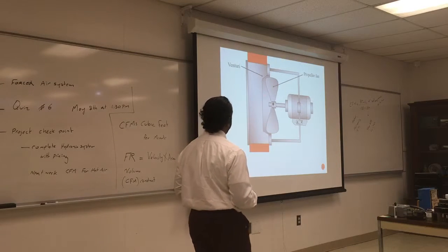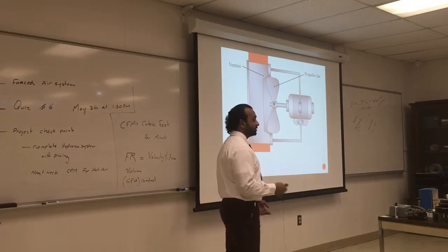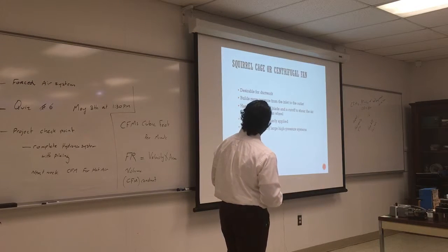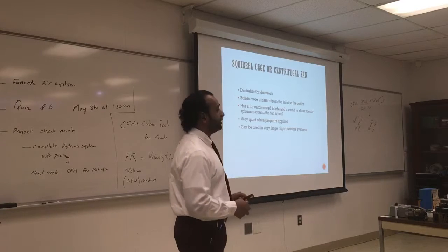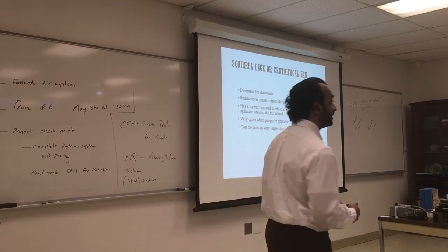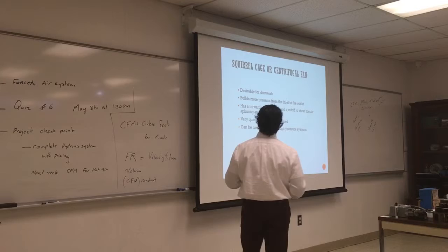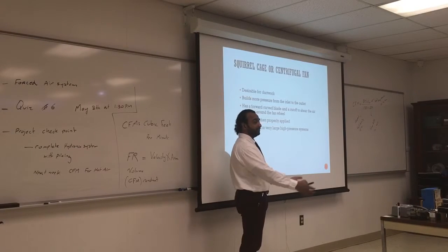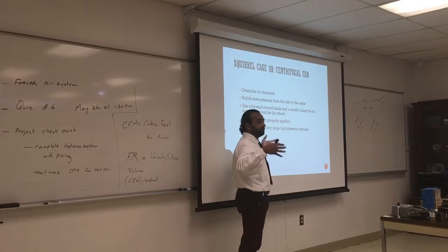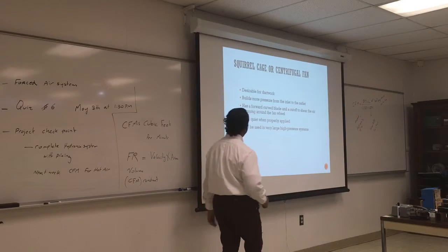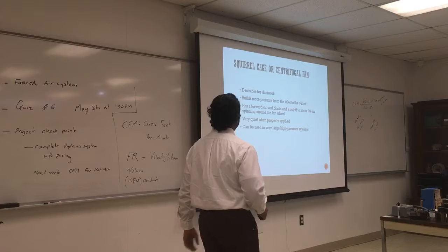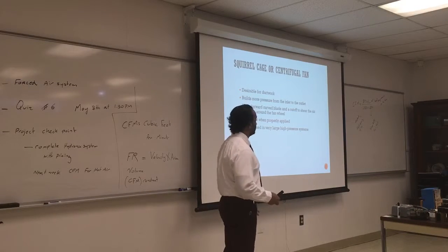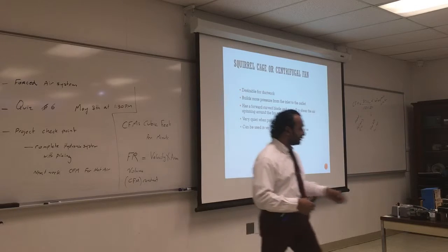This is the fan and the venturi. The fan provides a lot of pressure and pushes the air into the venturi. Squirrel cage, your centrifugal fan, probably you have seen those inside the duct. They are good for ductwork and they're designed to be inside the duct, so you take the fan outside completely with the box and you can put it inside and use the squirrel cage. Builds more pressure into the outlet. Forward curved blades, it actually looks like that.